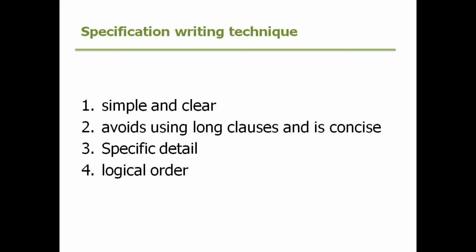What I'm saying there is that if you're putting up a fence or if you're putting up a building, try and keep the components and how you're going to start that process in order. Putting in a kitchen, putting on a roof. Keep the specification in an order that makes sense, from the preliminaries, from the groundworks, from the superstructure, from the roof, and then from the fit out. That type of logical order and sequence of writing the specification makes it simpler for everybody then to refer.